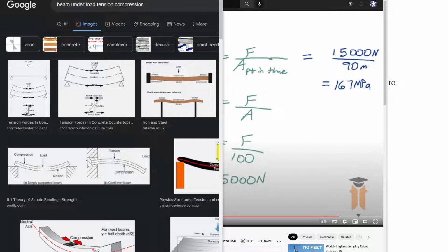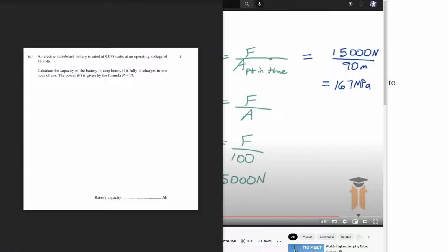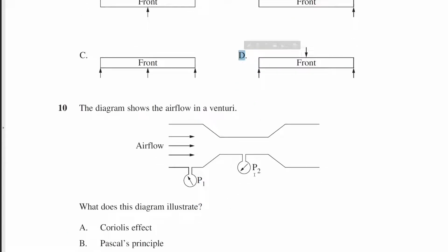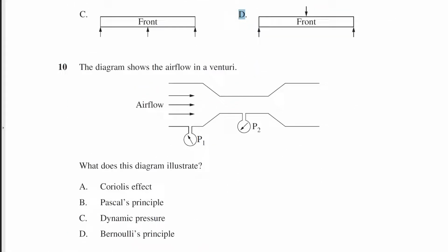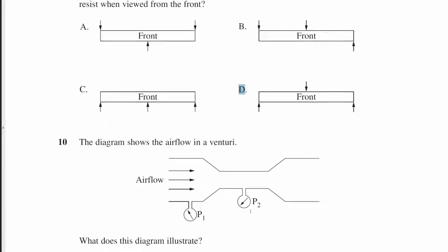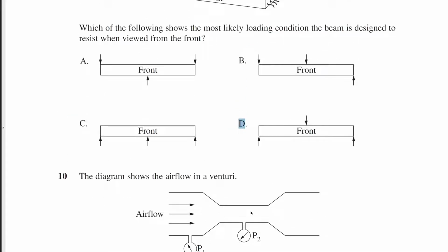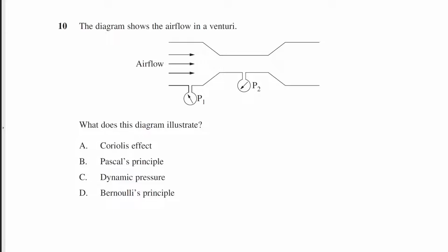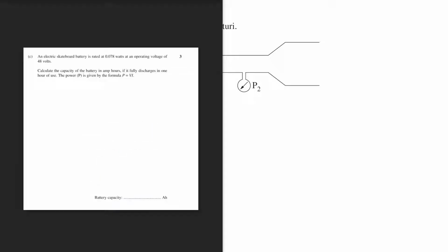Now we know that concrete is strong in compression, whereas it has effectively no tensile strength. So we need steel to act as the tensile member to provide that tensile strength. If the steel is on the bottom, that means it's loaded in a typical manner, which means the answer is D. Okay. Most people went with that, I think, just because it looks familiar. If they'd asked for a cantilever beam, and Copeland is on record as saying that he loves cantilever beams, just be aware. I think a lot of people would have got that one wrong.